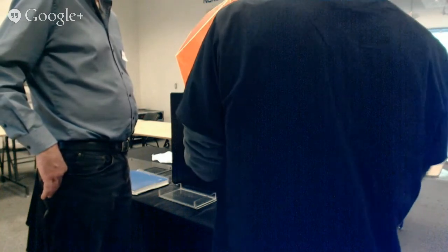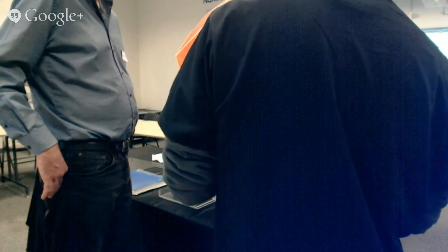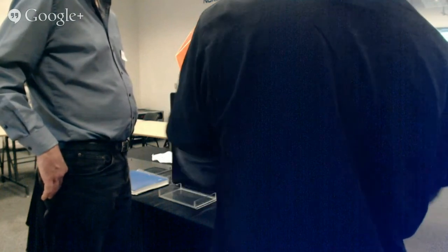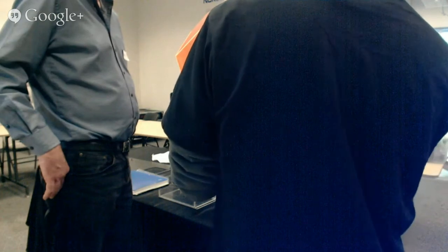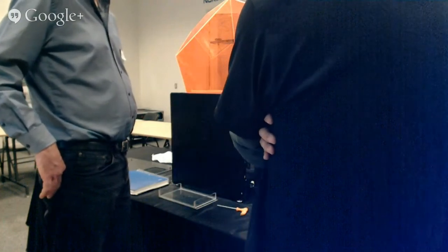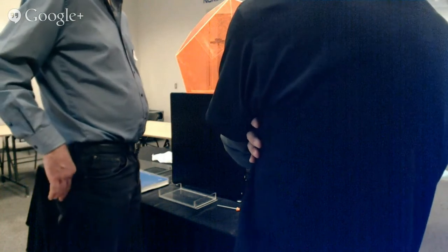If I change a parameter like the size of the stock, then I have to recompute it and recreate the fin. So I stopped doing that. It's relatively easy to add these in Meshmixer, and so I do this every time now, which is easier than modeling it every time. This is generated in Inventor, and then in Meshmixer I add the supports.